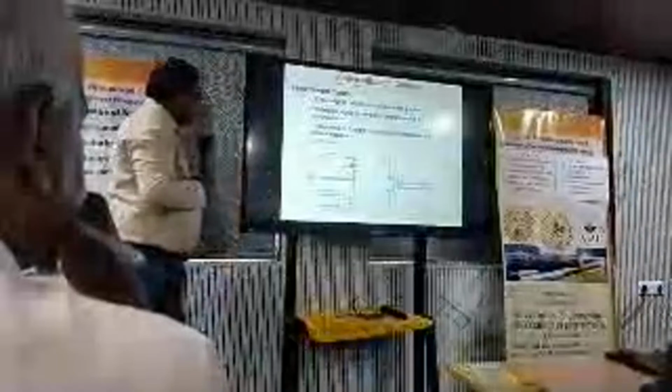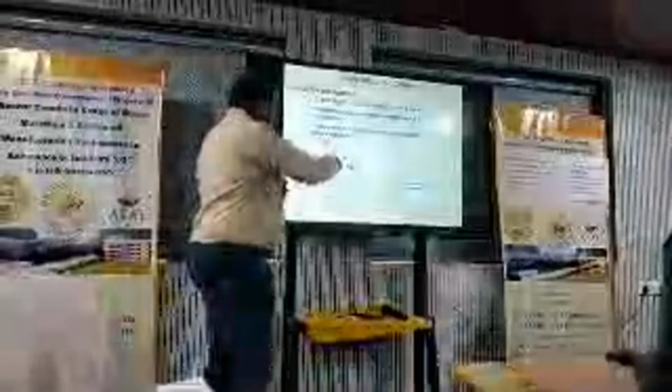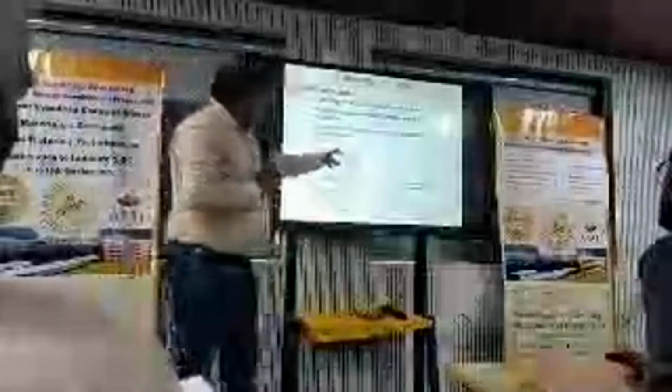Again, there are two types: active feed forward control and feedback control. Feed forward control is what we discussed initially. The input excitation is coming here. You take the same input excitation, and again you supply the required signal in the opposite direction. That is feed forward. We are taking the response from the input signal.